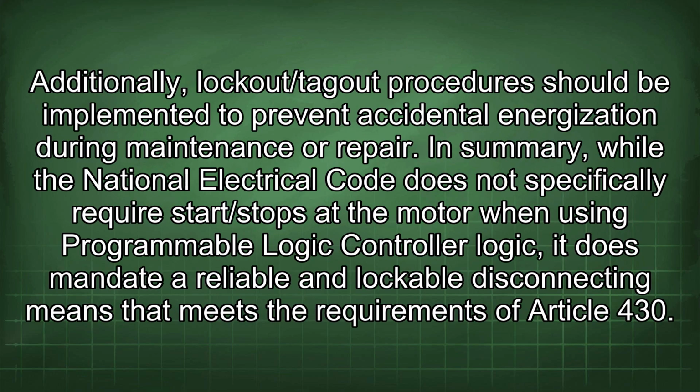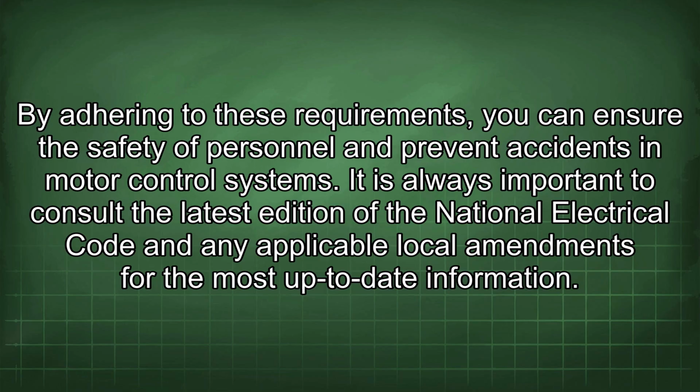Additionally, lockout/tagout procedures should be implemented to prevent accidental energization during maintenance or repair. In summary, while the National Electrical Code does not specifically require start/stops at the motor when using Programmable Logic Controller logic, it does mandate a reliable, lockable disconnecting means that meets the requirements of Article 430. By adhering to these requirements, you can ensure the safety of personnel and prevent accidents in motor control systems.